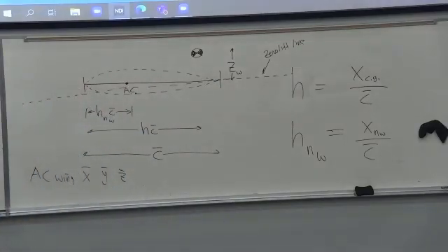So that's the line that if the wind is coming in parallel to that line, you get zero lift. This is what it's called, a zero lift line. Okay, so you're doing that. And then draw the actual relative wind coming in. And then this is defined to be the angle of attack of the wing.